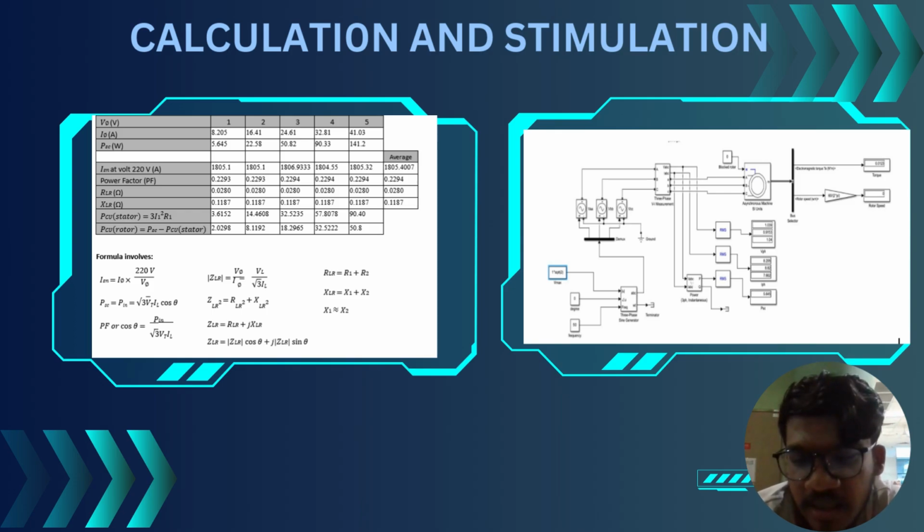Its leakage impedance. The rotor is blocked to prevent rotation, and balanced voltage is applied to the stator terminals where the rated current is achieved, as shown in the figure over there. Under the reduced voltage condition, the core loss current and the magnetizing component of the current are quite small percentages of the total current. So next is the table part over there.